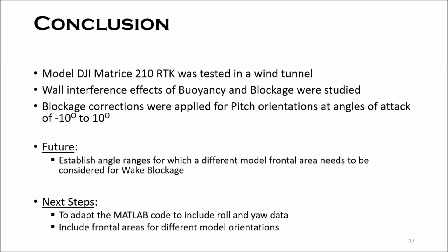A future scope from this study may be to understand the ranges of angles that should be considered when applying wake blockage corrections, which involves the model frontal area. Buoyancy effects were found to be negligible, so the buoyancy corrections were not included. The further application of this project would be to adapt the calculation method to include roll and yaw data, as well as to include frontal areas for different model orientations.